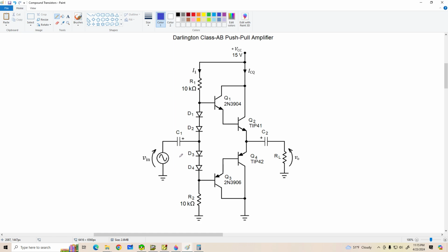Okay, but anyway, I think you get the idea how this is going to work. It's a pretty common circuit. One thing we have to watch for is that these transistors tend to oscillate. So when we power this up, you might see an output signal that's in the megahertz range, and that's because these transistors are oscillating. So you've got to be really careful about your wiring and supply bypassing. I'm going to talk more about that later.